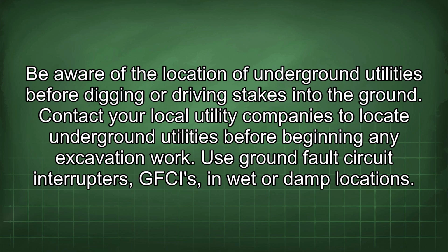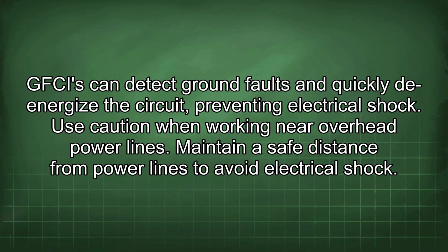Use ground fault circuit interrupters, GFCIs, in wet or damp locations. GFCIs can detect ground faults and quickly de-energize the circuit, preventing electrical shock. Use caution when working near overhead power lines. Maintain a safe distance from power lines to avoid electrical shock.